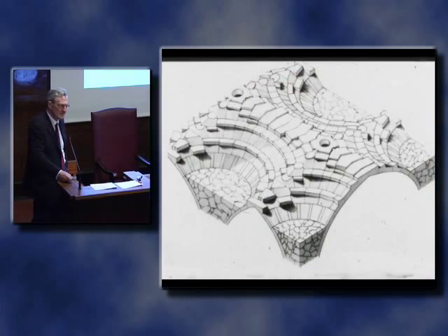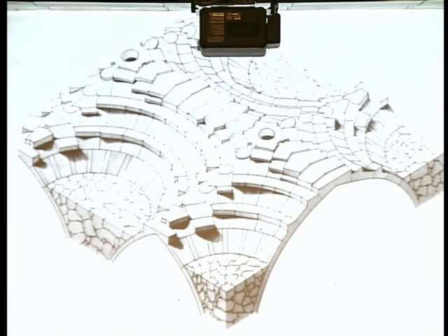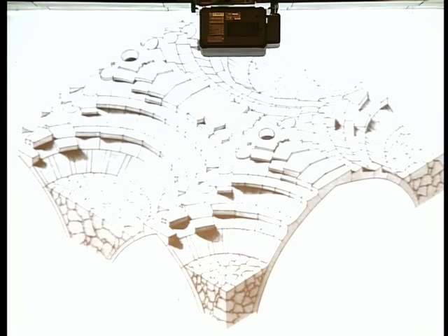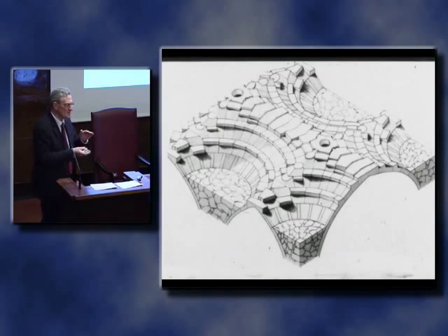The stereotomy of this structure is enormously complex in order to construct such a doubly curved membrane, if you like, to actually put it together, compared with the idea of a dome of just 2 bricks thickness, which you just lay one on top of another, the timbrel vault construction.